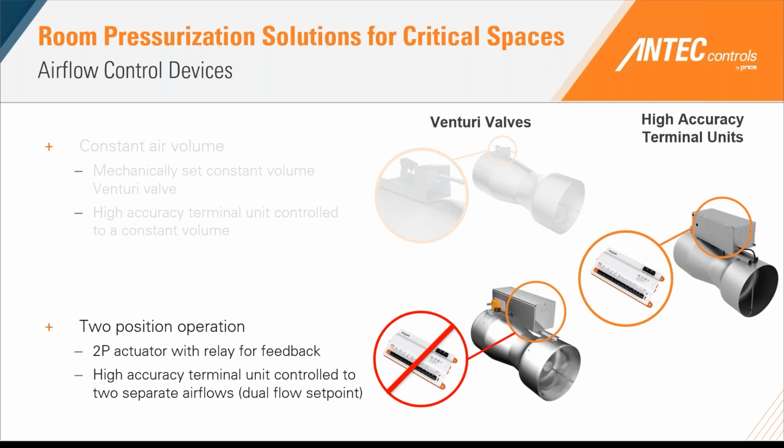On the opposite end again though, because your high accuracy terminal unit needs to be able to measure airflow in order to control to a set point, you will still need to have a controller and an actuator in order to achieve a 2-position type operation.